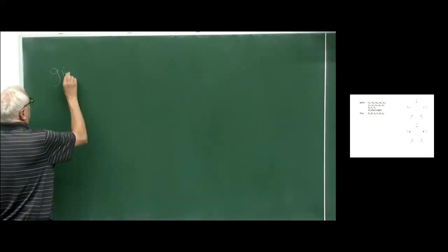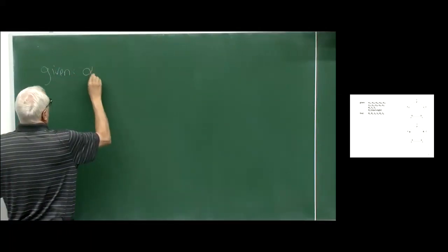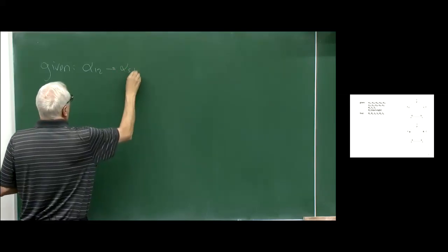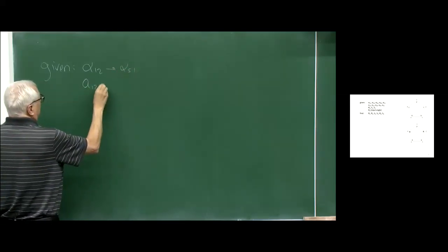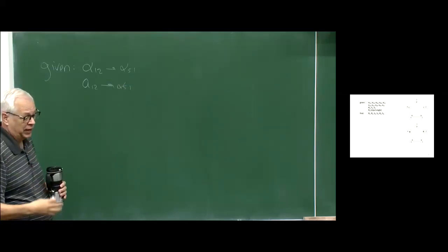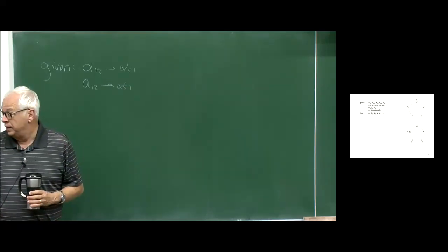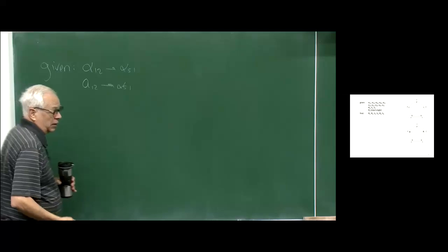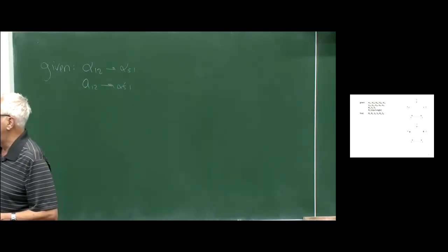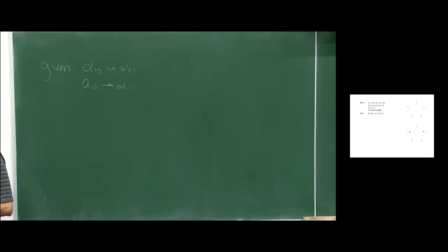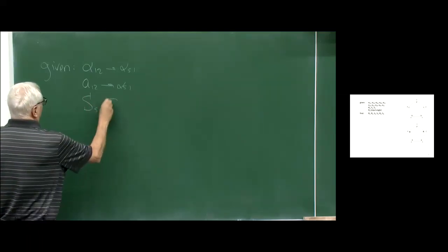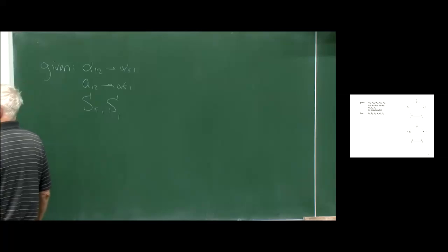But for this particular spatial mechanism, we're going to be given all the alphas. So that's alpha 1, 2 through alpha 5, 1. And we're given the link lengths, based on our choice of S vectors and A vectors. When I look at the mechanism, again, this is the 3D mechanism. Where the revolute joints are, we know the joint offsets. So I'm going to say S5 and S1. That's where the 2 revolutes were.